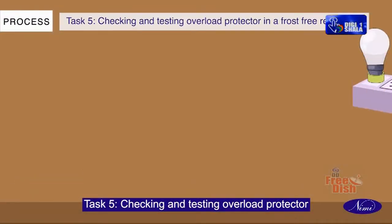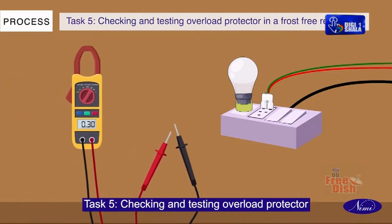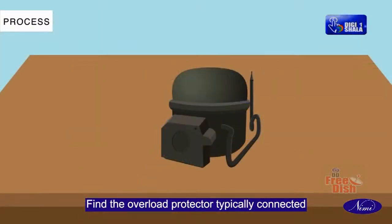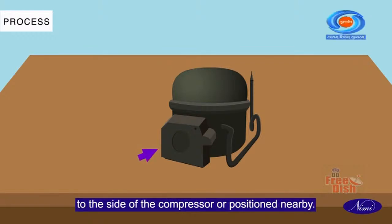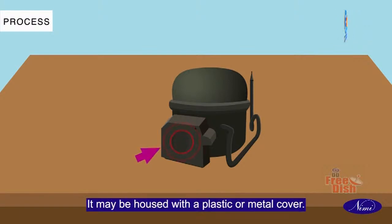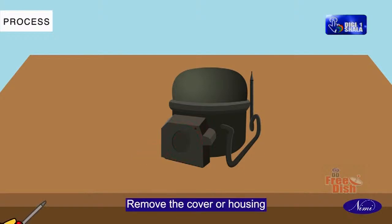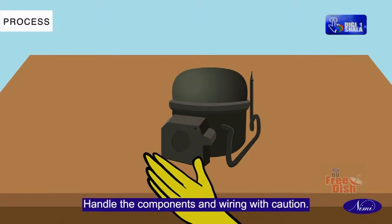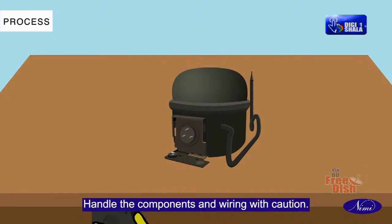Task 5. Checking and testing overload protector in a frost-free refrigerator. Find the overload protector typically connected to the side of the compressor or positioned nearby. It may be housed with a plastic or metal cover. Remove the cover or housing protecting the overload protector. Handle the components and wiring with caution.